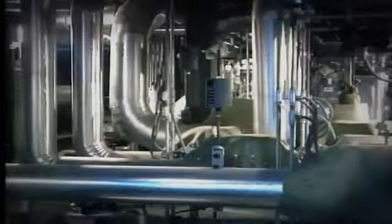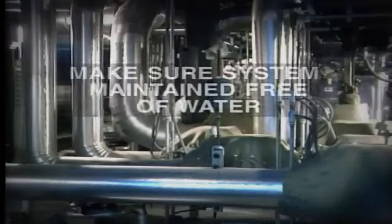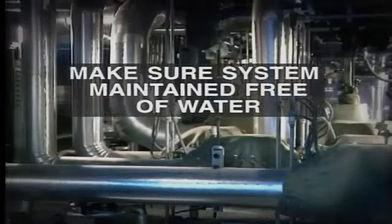In operating any of the steam systems, one of the most important operating requirements is to make sure that the system is maintained free of water. In this segment, we have looked at typical steam systems, but of course all plants are different. Make sure that you become familiar with all of the features of your various steam systems. That is main steam, reheat steam, extraction steam, and auxiliary steam. Now at this point, it's time for a break, so please switch off the tape and review this material in your workbook.